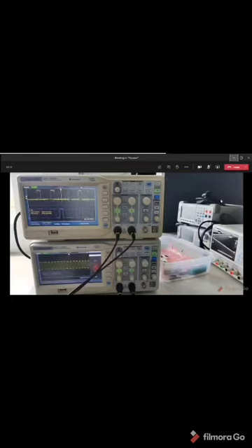Here we can see that for one clock cycle we are supposed to get our output. We are getting our output, but we are also getting extra spikes. That is our false output. That is because our noisy input and the state conditions are affecting our outputs. That is why we are getting so many false outputs, and that is affecting the output that we get.